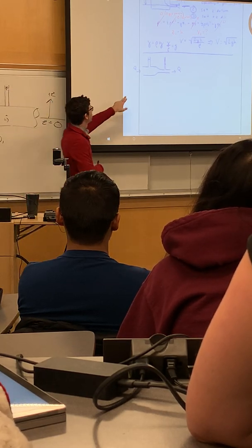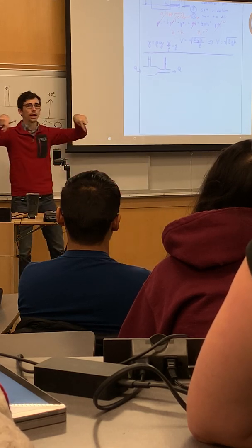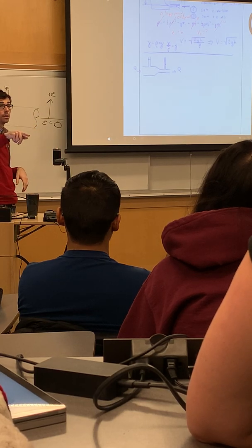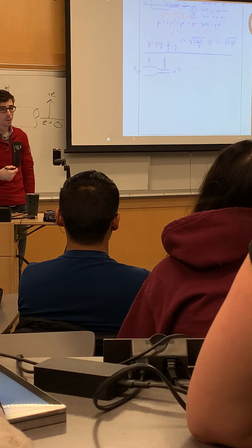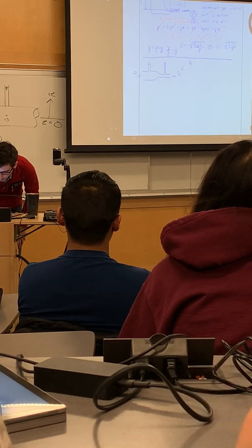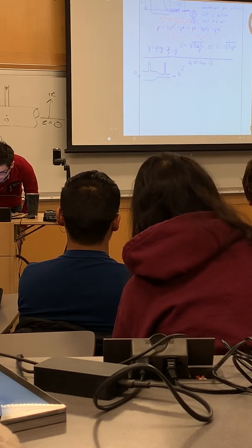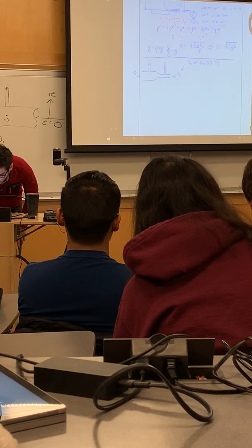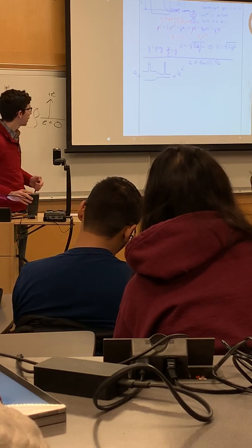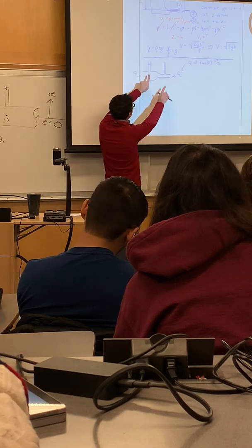We have a flowing tube, flow flowing through a tube with two piezometers attached at the larger diameter portion of the tube and the smaller diameter portion of the tube. What's Q? Q is the flow. So I'm going to use the letter Q to denote flow, right, with units length cubed per time. And we'll work a little bit more with flow and velocity relationships in a moment. So if we have flow moving through these piezometers.